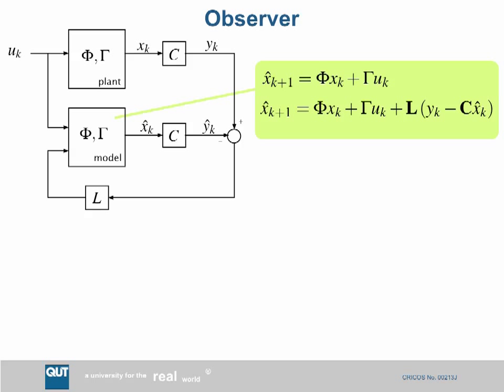So this is the dynamics of the estimator, of our model. Simply copied it from up there and rearranged it a little bit. I've lumped all the xk terms together. And so this then are the closed loop poles of our estimator. And I think you probably did this for a continuous time estimator. Yep. So we have the closed loop poles. So this is one of the design parameters.